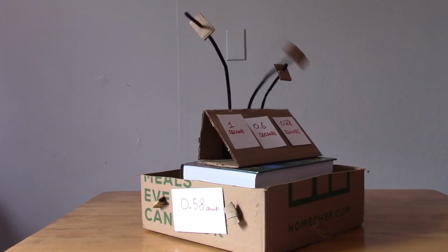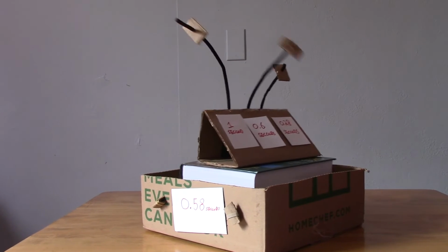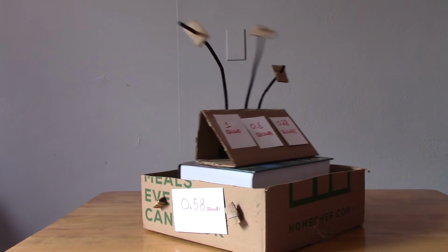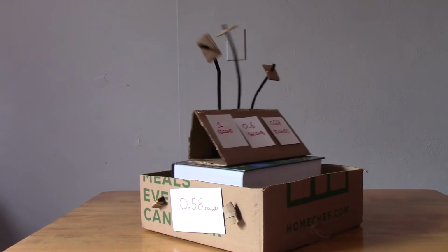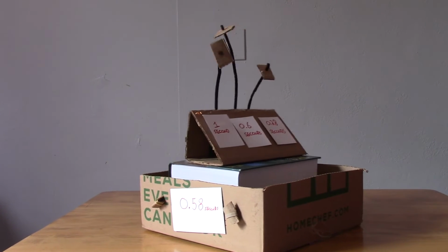As you see here, the base of all the pipe cleaners must move with the earthquake, but the structure with a period of 0.6 seconds is moving much more. This effect is called resonance and is happening because the ground motion and fundamental frequency of the structure are very close. If this were a real structure, it would be dealing with significantly higher forces than the other structures.